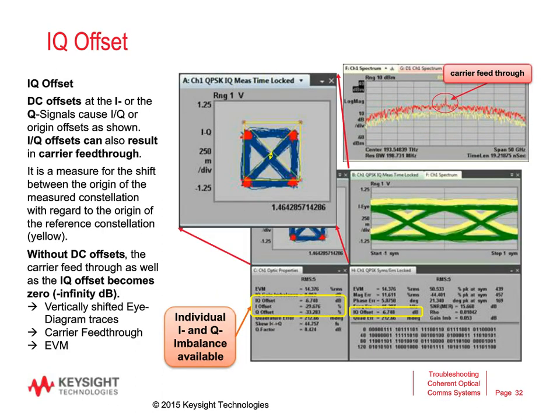Another measurement that's often done is what we call the IQ offset. The IQ offset is an offset in the DC component of your driving signals. Again, we see the two eye diagrams here, but unlike the pictures we saw before, now we have just different DC levels in the two eye diagrams. So the green one seems to be slightly lower than the yellow one. That means my constellation is not centered in the middle of the constellation plane here.